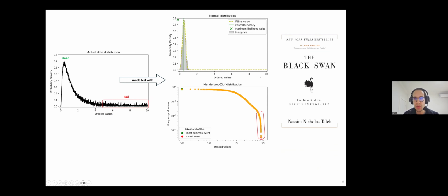And contrarily, what we would have liked to focus on was these tail events. So we came up with a function called Mandelbrot-Zipf, which is particularly suitable for modeling rare events. We got the inspiration from this book in which Nassim Taleb discusses data and rare events in the context of financial crisis, and we adopted it into pitting corrosion. I must say here that this modeling is quite complex, based on fractal theory, but the importance is that it is indeed able to fit the rarest events, in our case, pitting corrosion events.